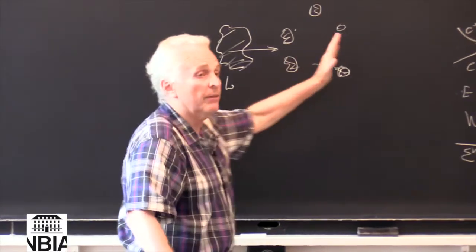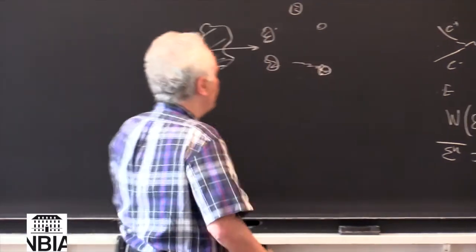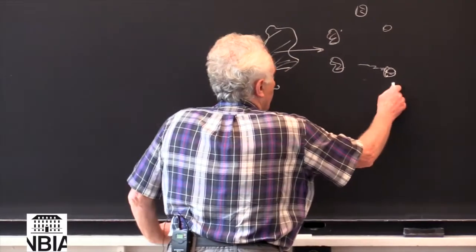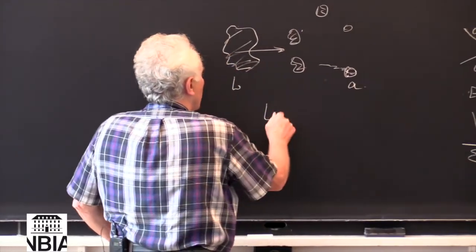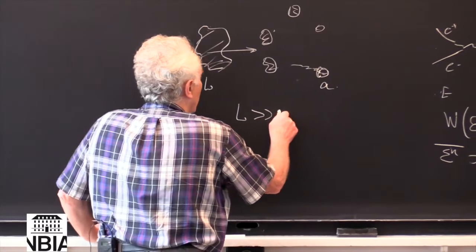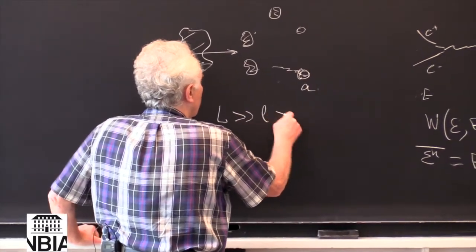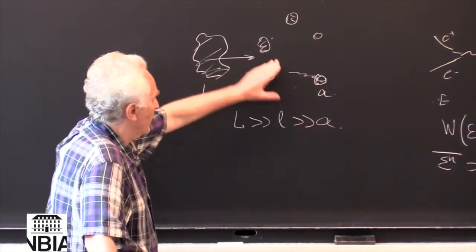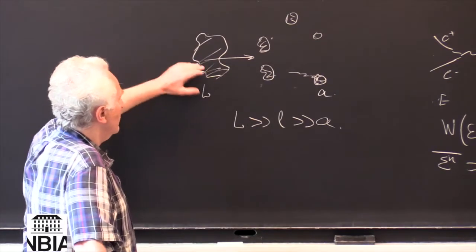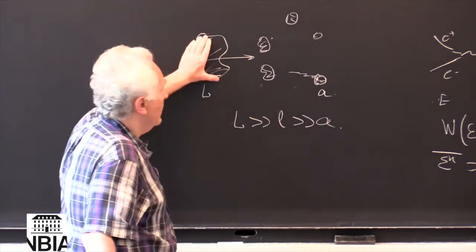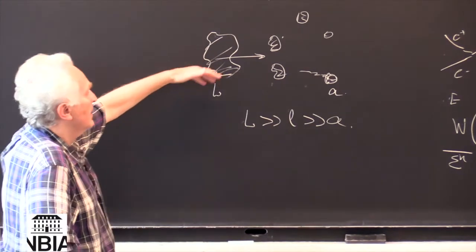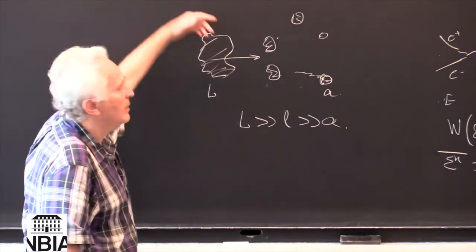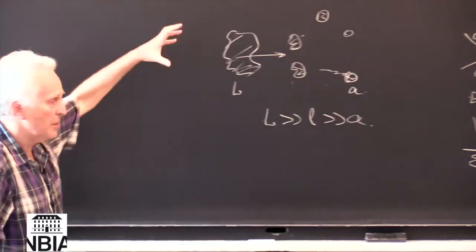Viscosity is the ultraviolet cutoff in this theory, and it happens at some scale a, so that the inertial range is the intermediate range where dissipation is negligible, and we also don't feel directly the details. We can hope for universality, that the physics here will be independent of how precisely you generated these original large fluctuations.